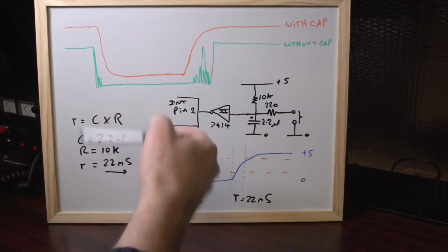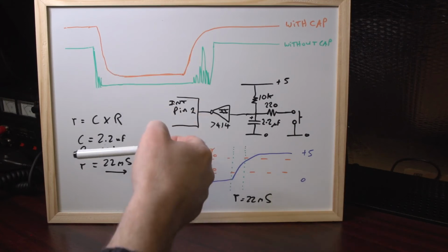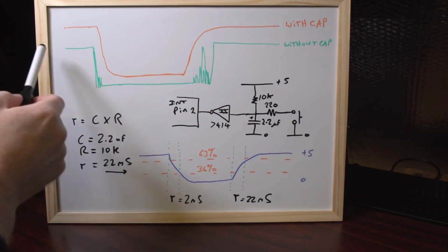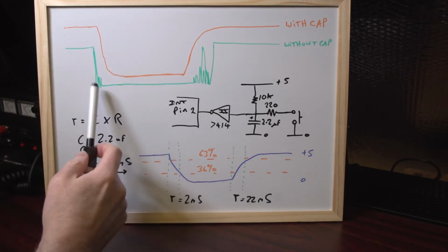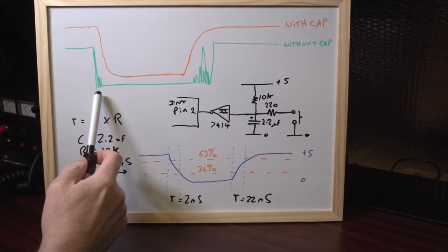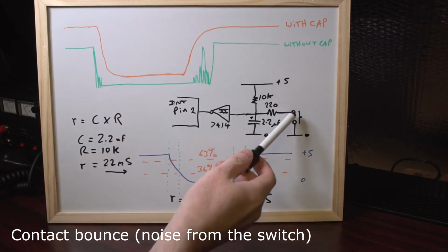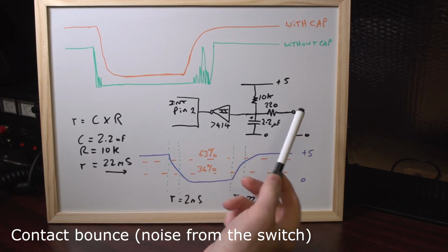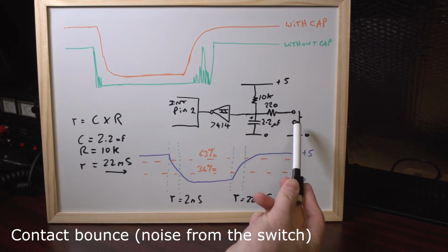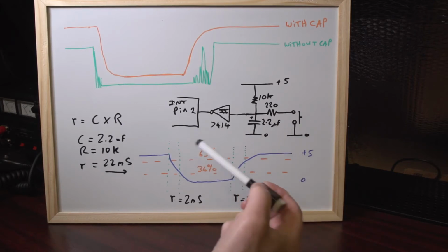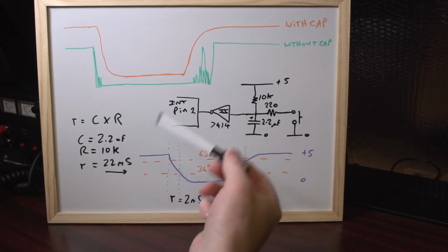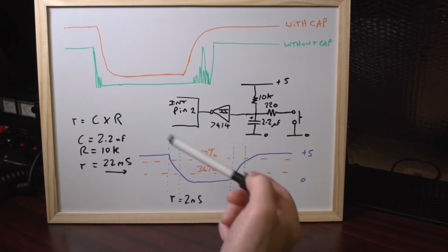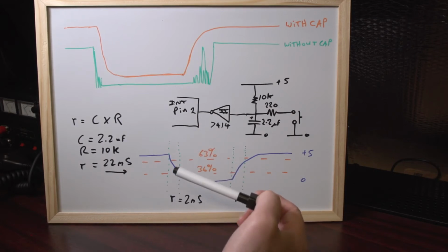You actually get a brief moment, within about a millisecond or 2 milliseconds, of a little bit of noise when you push the button. It's not a clean 1 to 0 transition. This noise is what we refer to as contact bounce, because inside the switch itself, mechanically, there are 2 metal strips. When you push the button, those metal contacts rub against each other a little bit and have an action of bouncing, which is why we call it contact bounce. It happens very quickly, but it's there, you can see it on a scope.